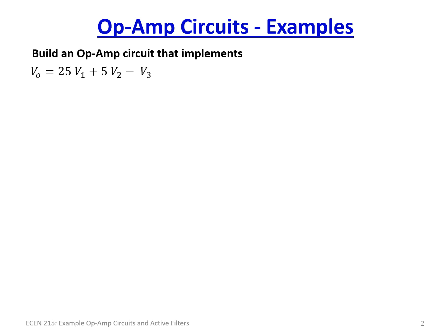Now, given this, what could we use? Well, we had an inverting amplifier, and we also had a non-inverting amplifier. We had an integrator, a differentiator, difference amplifiers, and an inverting summer, which is good because with the inverting summer you can sum up to n different stages. So that will take care of the V1, V2, and V3 summation. The only problem is it's a negative summation.